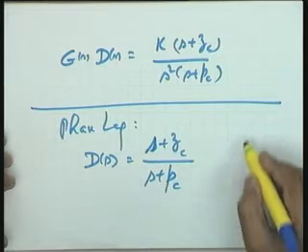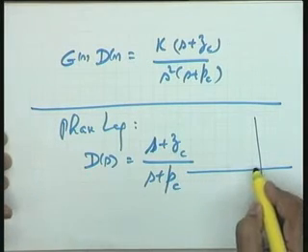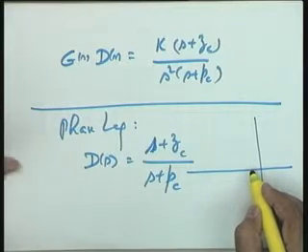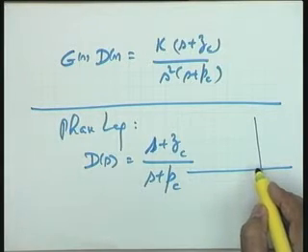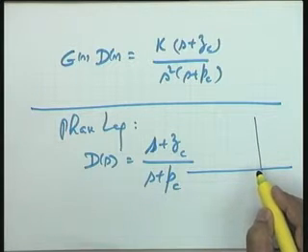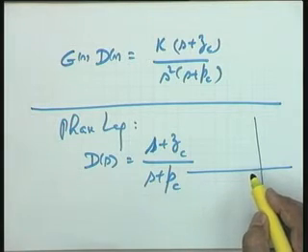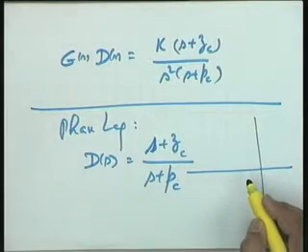This is the lag network model, but the pole-zero pair now is of this nature. A pole close to the origin, not necessarily at the origin. If you place a pole at the origin, it is the special case, and that is the case of a PI controller. You know that a PI controller means the pole is placed exactly at the origin.